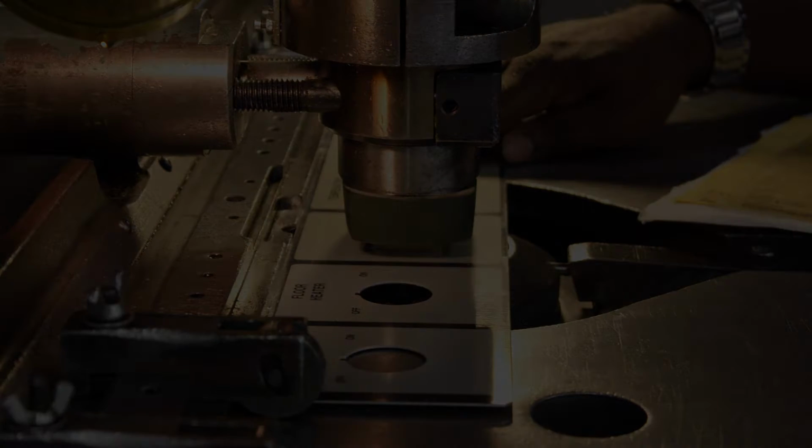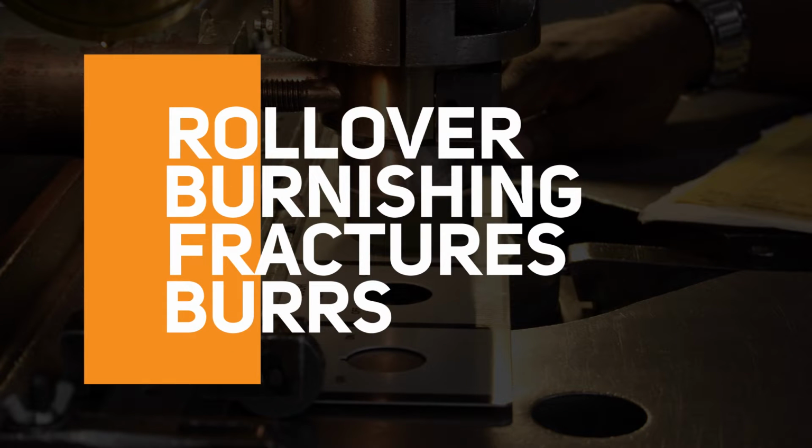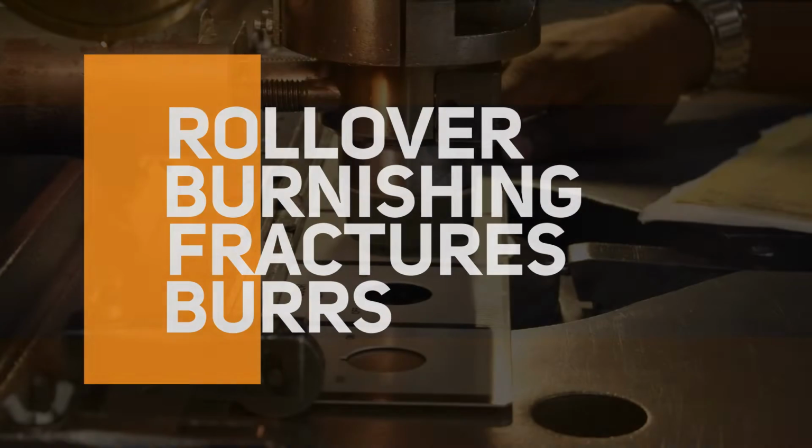Punched parts will have one or more distinctive characteristics, including rollover, burnishing, fractures, and burrs. As the punch engages the sheet metal, it pulls the material downward, slightly drawing the material into the clearance, which creates rollover. As the punch continues to penetrate and shear, the upper portion of the material becomes locked between the punch and the die, which creates a burnished area before the remaining material fractures and separates completely.